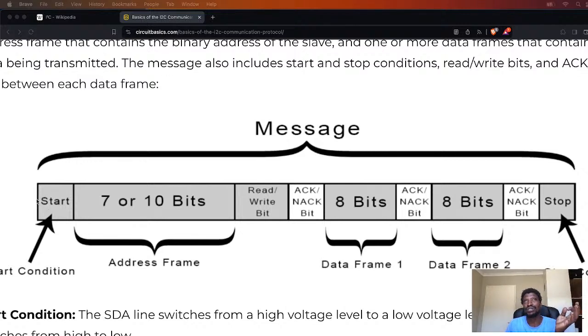So there's no mode, it's who starts the start. Whoever begins the information is going to be regarded as a master, okay? And then from there on, they have certain responsibilities. Usually you will have 7, sometimes you will have 10 bits, but for the purposes of this talk, we'll just talk about the 7-bit one, so that it's simple and kind of concise.